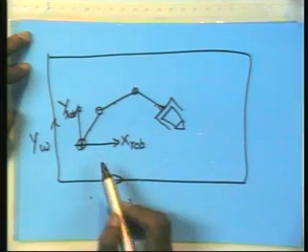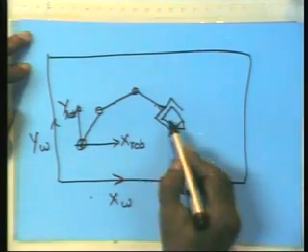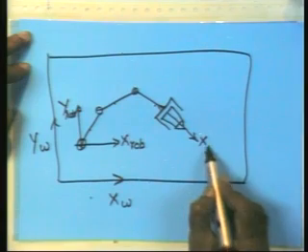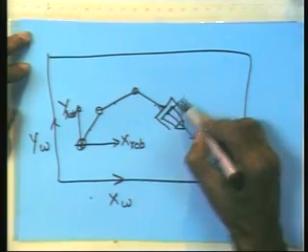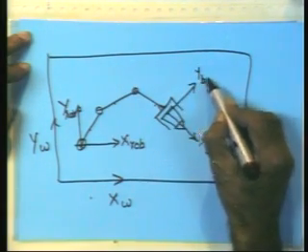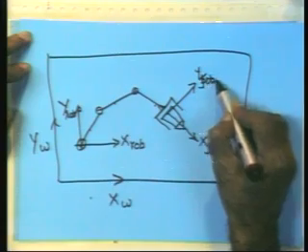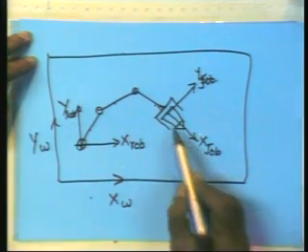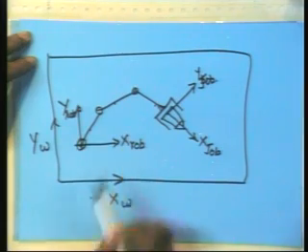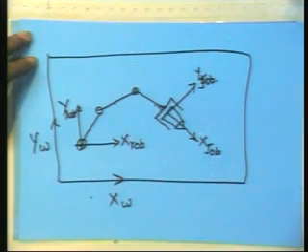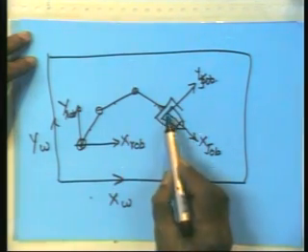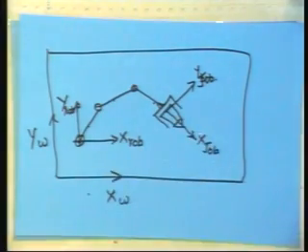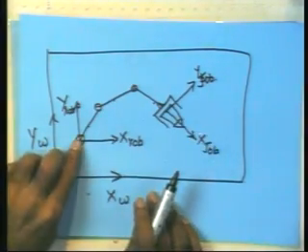Okay. So as you go, I can fit a coordinate frame to the object also. I will call it job. Then the inclination, the orientation of this object, is the inclination of the X job axis with the X robot axis. So I will paste a paper containing these two axes on the job. I will paste the paper on the base of the robot.